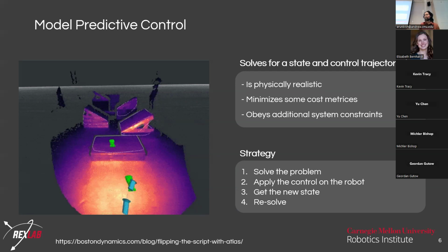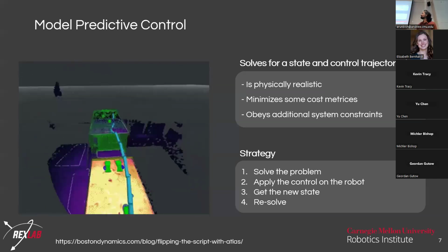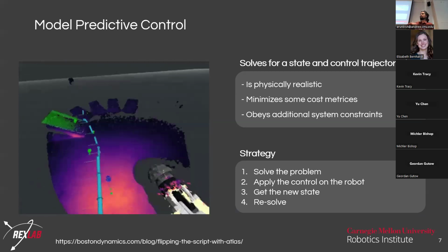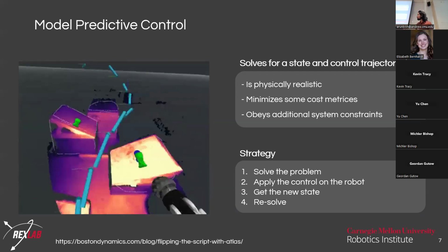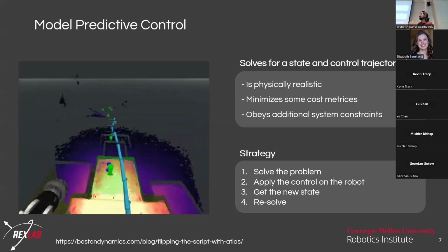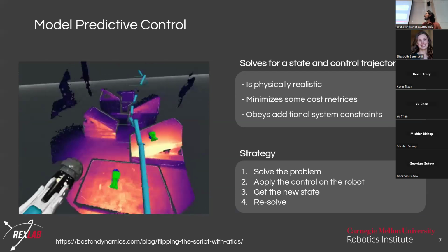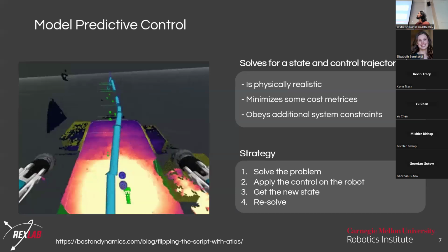And a really common example of doing this with nonlinear model predictive control and sequential quadratic programming is the biped robot Atlas from Boston Dynamics. So here you see a GIF of it doing parkour, where that set of blue arrows is this future trajectory that's being planned over and optimized over. And this problem, you can pretty much express every time step by linearizing everything and turning it into the QP form. And this is kind of an existence proof that we can do whole body really fast MPC using QPs.